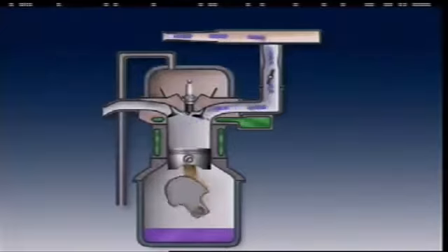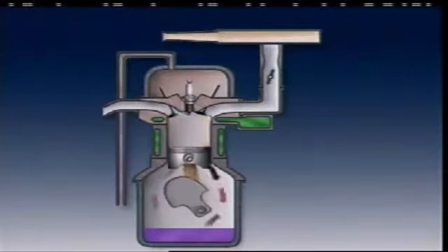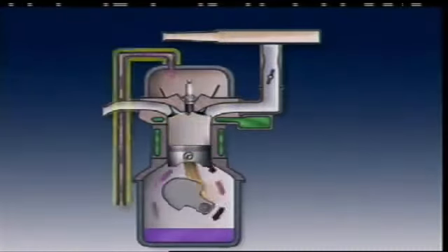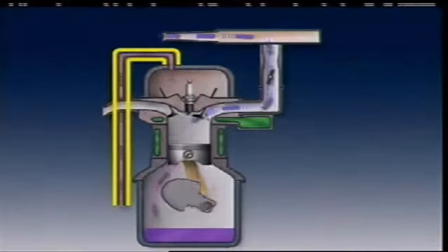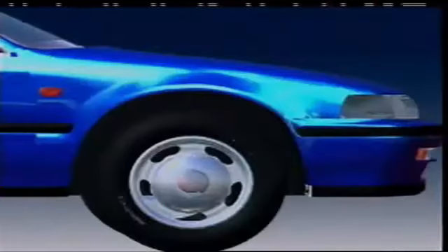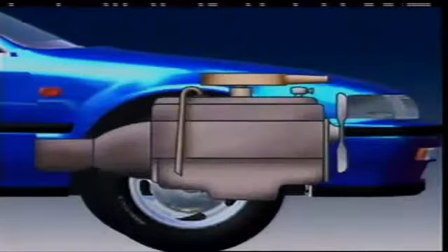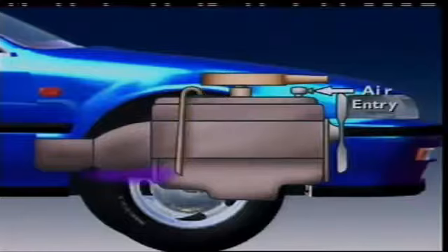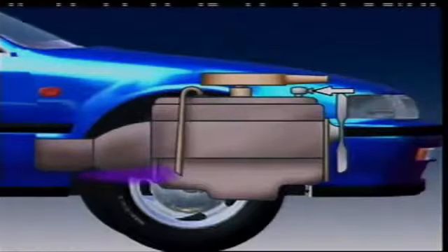When the engine reaches its full operating temperature, the water and fuel evaporate. To prevent pressure build-up, the crankcase must be ventilated. In older vehicles, crankcase vapors were vented directly to the atmosphere through a breather tube or road draft tube. It was shaped to help draw the vapors from the crankcase as the vehicle was being driven.